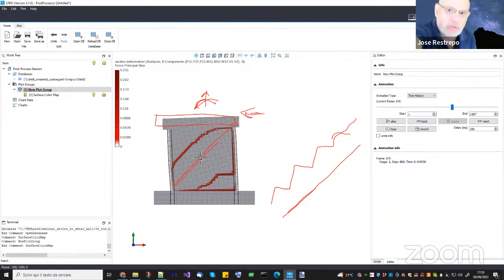Now, where do we also find this type of walls? In industrial facilities, power plants or so, they're comprised of many complex low rise, high rise walls, so they're not necessarily a building thing. They're also in the old piers of bridges that instead of columns had walls and they were lightly reinforced. So we have a few of those in California as well. So they're not the bread and butter, but they are not uncommon either. It is important to find a way to capture their behavior.